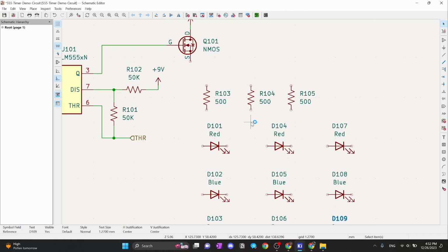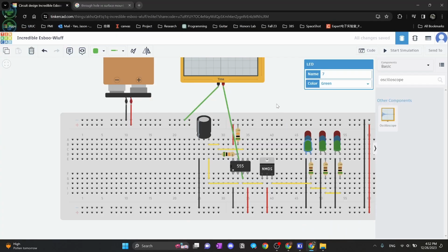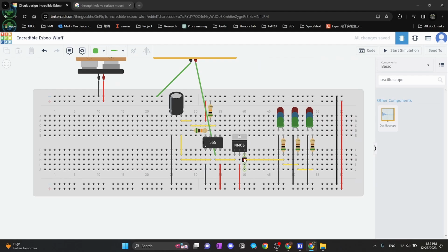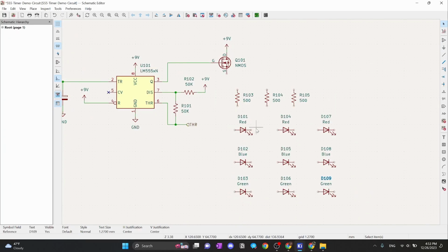All right. So basically what's happening here on the breadboard is that the source pin goes into a resistor, then goes through a bunch of LEDs in parallel, and those LEDs are connected to ground. Again, that's a fact for all 3 sets of LEDs over here. So let's just do that real quick.